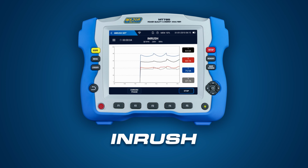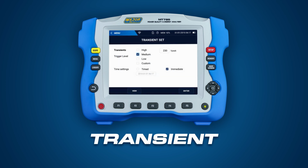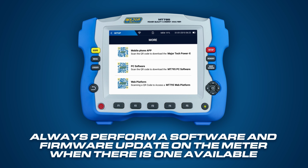Set up inrush current testing and record the data. You can also record data for flicker and set limits for transients, dips, and swells from the main menu. Always perform a software and firmware update on the meter when there is one available.